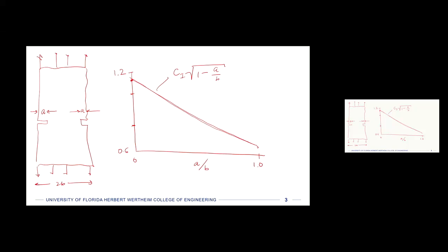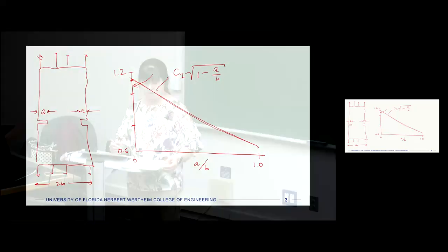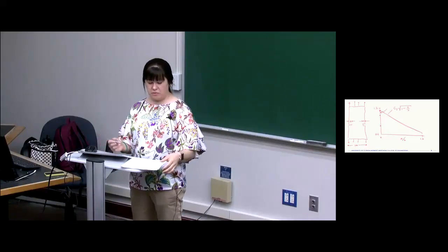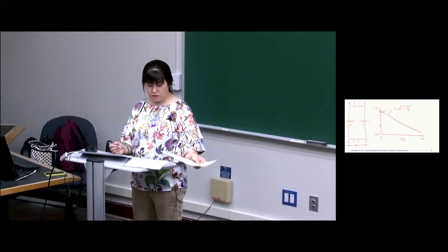So you can see now that if the crack is very small, then we have a different type of effect, where we might even calculate a C that's very close to 1. So you can start to build your intuition as to how the geometry of where the crack is affects this fracture toughness. And there's actually a nice problem at the end of the chapter, which I think I'll put in a problem set, that has you compare, if the same size of crack is in the center of the plate versus the edge, which is the more intense situation and would cause failure first.